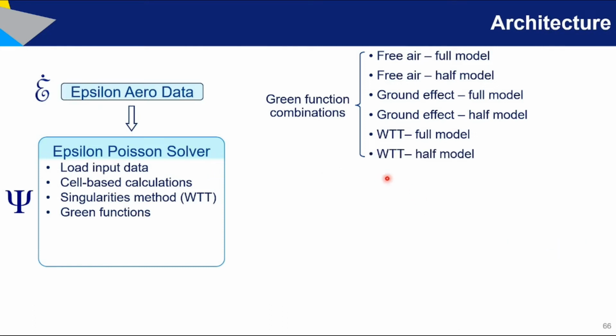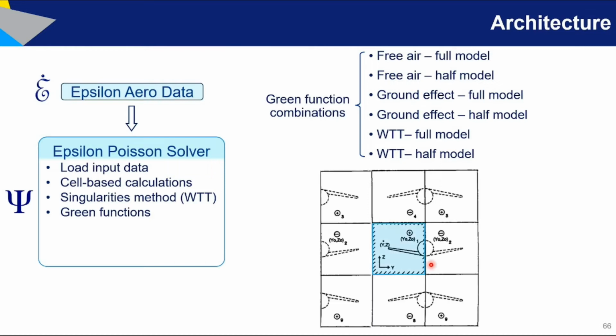The other case is wind tunnel testing with half model. This is your wind tunnel walls, this half model that you're testing. And as before, you have to introduce the presence of the wall numerically. So you introduce a mirror of each one of the walls. And as before, you need to add several layers. And it's the same as the full model.